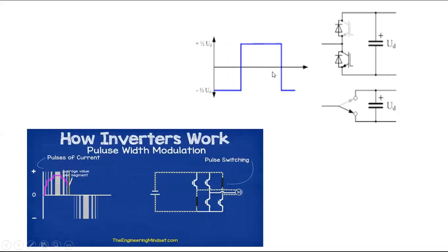So we say the inverters are there. What is the complete name of the inverter? As per the syllabus I am moving, H bridge inverter. H bridge contains certain SCRs. Okay, you can see here. When these SCRs are turned on and off, we generate the AC signal. But that AC signal will be in the shape of a square wave.